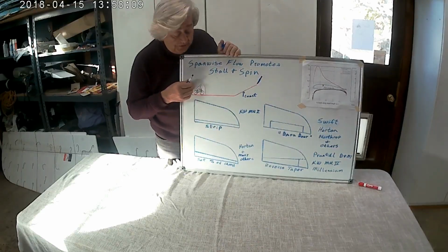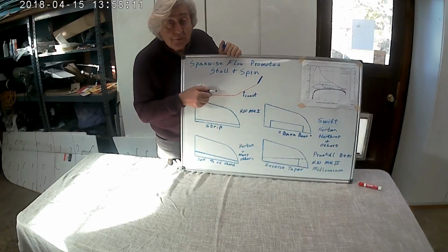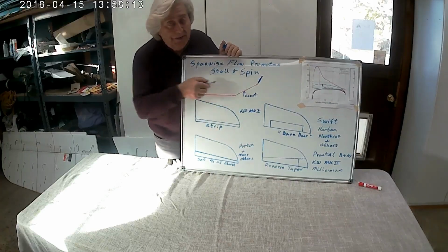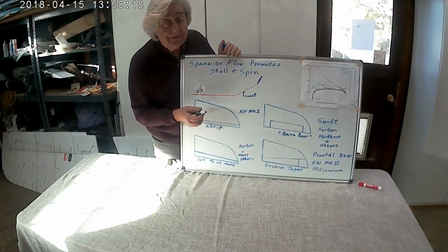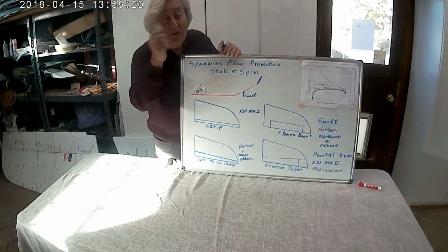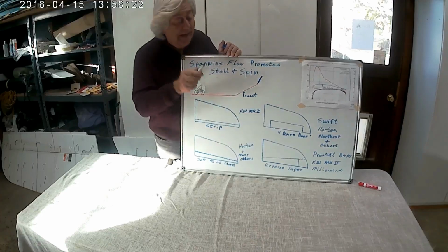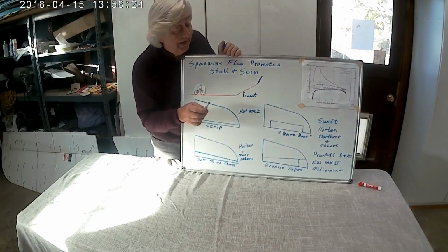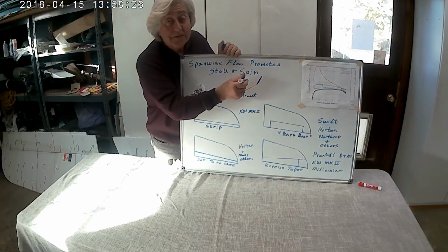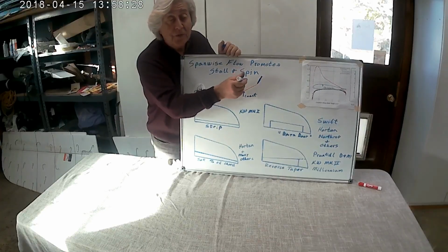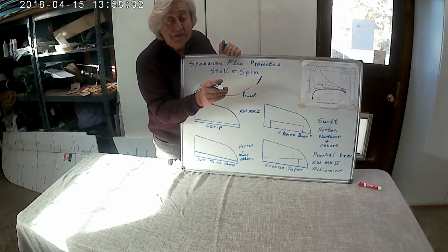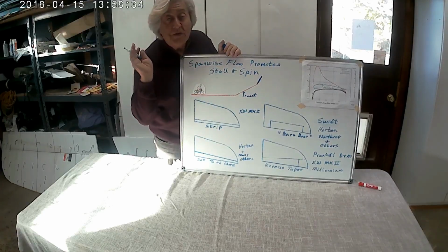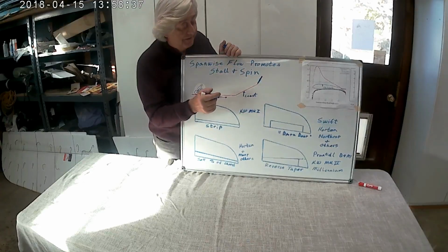Remember, if this were airflow, there's a bunch more bicycles right behind him. You got all these air molecules backing in, backing in, backing in. He can't roll backwards down the hill. There's a whole bunch of guys behind him going, get going, get out of the way. His easiest way to get out of the way is to go spanwise. Because that's where the wingtip is, that's where his neutral pressure situation is, and he's got a whole bunch of other air molecules inboard that are also trying to go out to the wingtip.